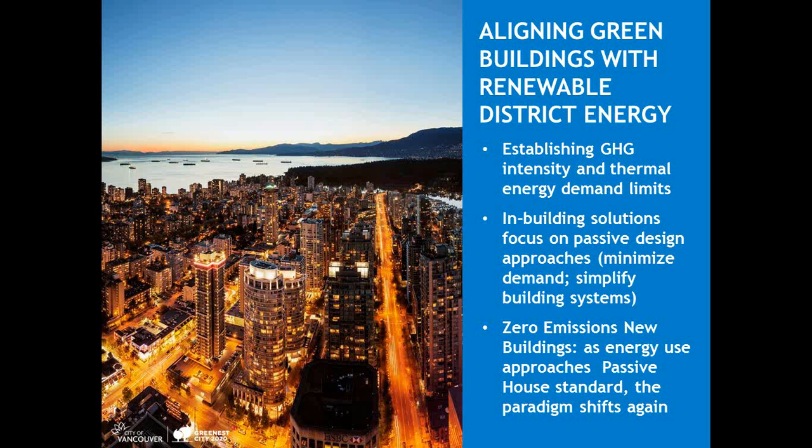We are making a shift, though. One of the things we've come to realize is that within green buildings, the importance is not to emphasize as much equipment efficiencies and renewable technologies at the building scale, but really shifting hard now to much better building envelope performance. Historically, Vancouver, and you can see pictures of Vancouver here, has a large amount of glass, and a really immature design community understanding of thermal bridging currently, and so that was one of the reasons for driving this thermal energy demand limit. These passive design approaches really can minimize demand and very much simplify building systems, which we're coming to understand means simple operations, especially in the residential sector, which is the majority of our large-scale development, not commercial. Simplifying those systems is super important to making sure you achieve your outcomes and maintain them.